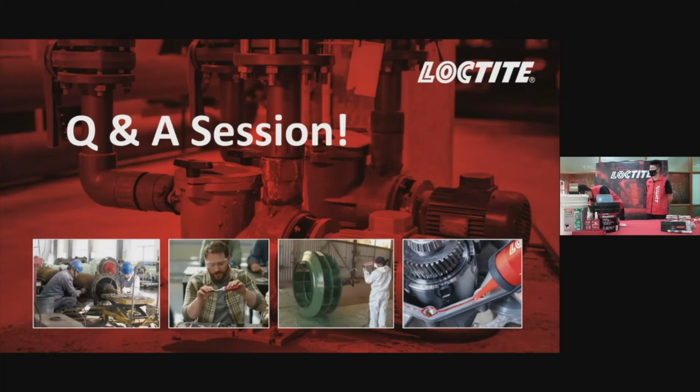So I have one question. I think he is asking what is the operating temperature for LOCTITE EA3478. Okay, so which means it's the superior metal. For this superior metal, the application temperature is around 120 degrees. But if you are looking for higher applications, for example 130 or 150, we have the high temperature superior metal. Or if you're looking even higher, we have LOCTITE MR2000, which is able to be used for metal rebuilding applications up to 1000 degrees Celsius.